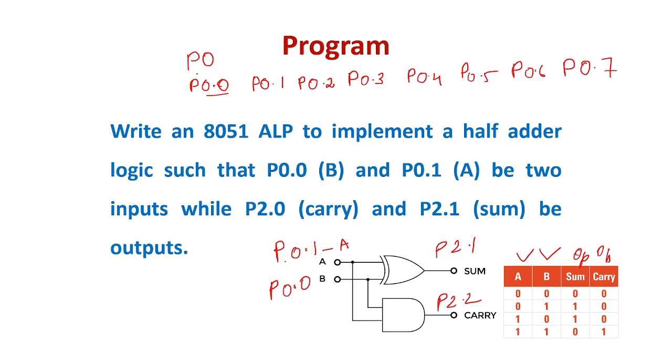You can observe that you have two outputs, sum and carry. The carry logic is performed with the logical AND operation. The sum is performed with the XOR logical operation. For AND logic, the 8051 microcontroller has a bit oriented instruction, but for performing XOR there is no specific instruction. There is no bit oriented XOR instruction.